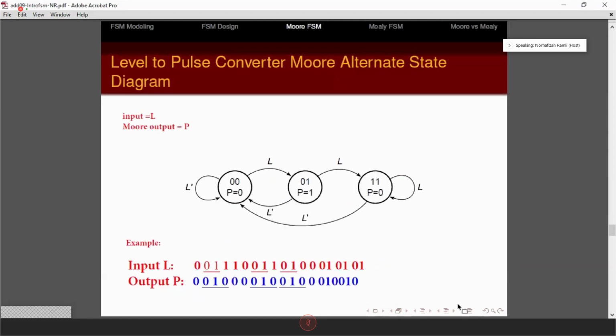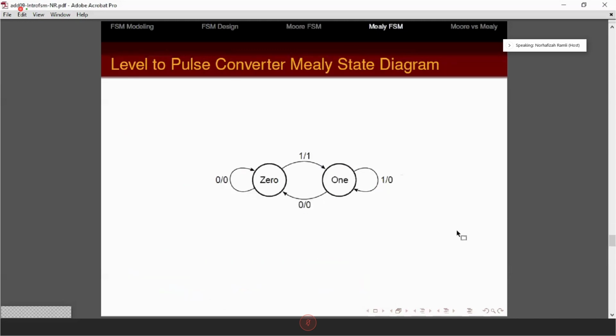I cannot do it. So look at it. When you see a 0, 1 transition, the output will have 1. And then if you have 1, 1, 1, nothing will have the output. Now you check also, you see the 1, 0, 1 again. You have the output 1, nothing happened. Again, you see the edge, the output is triggered. You see the edge, the output is triggered. And this one also triggered, but I didn't put it there. I cannot put it there because this is a PDF.